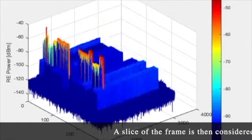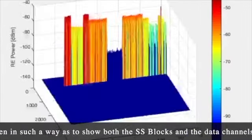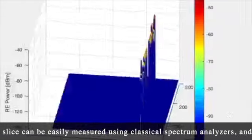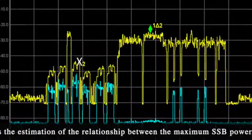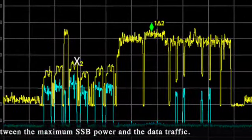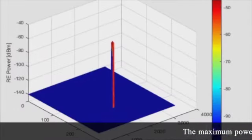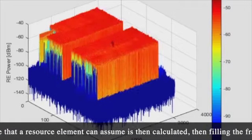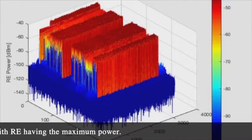A slice of the frame is then considered, chosen in such a way as to show both the SS blocks and the data channels. This slice can be easily measured using classical spectrum analyzers, and allows the estimation of the relationship between the maximum SSB power and the data traffic. The maximum power value that a resource element can assume is then calculated, then filling the frame with the maximum power.